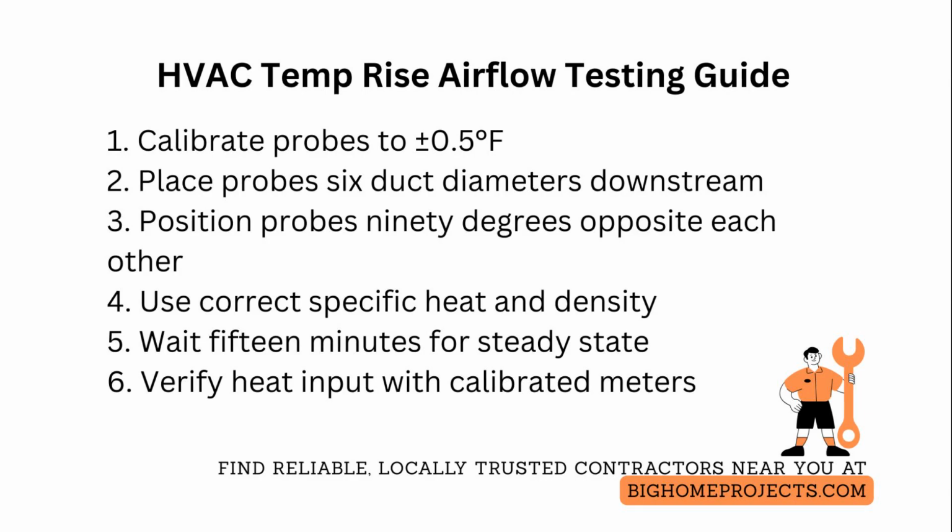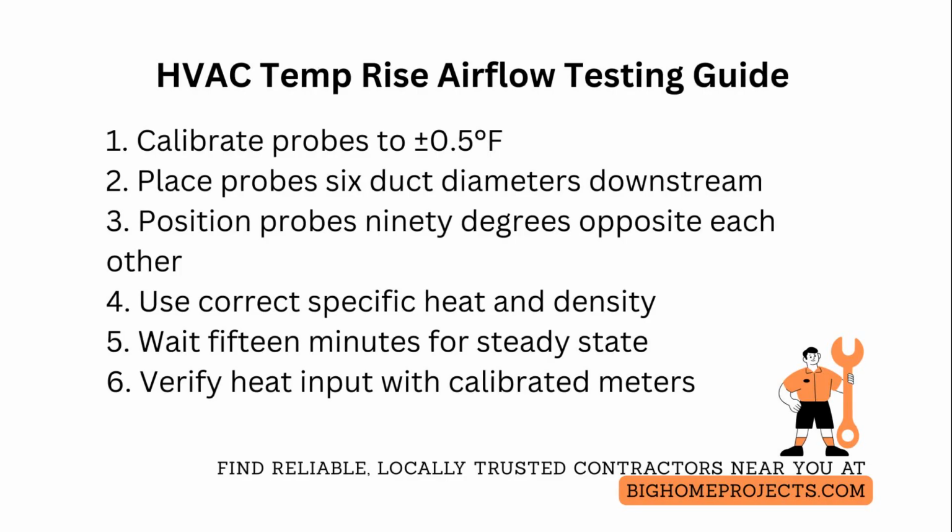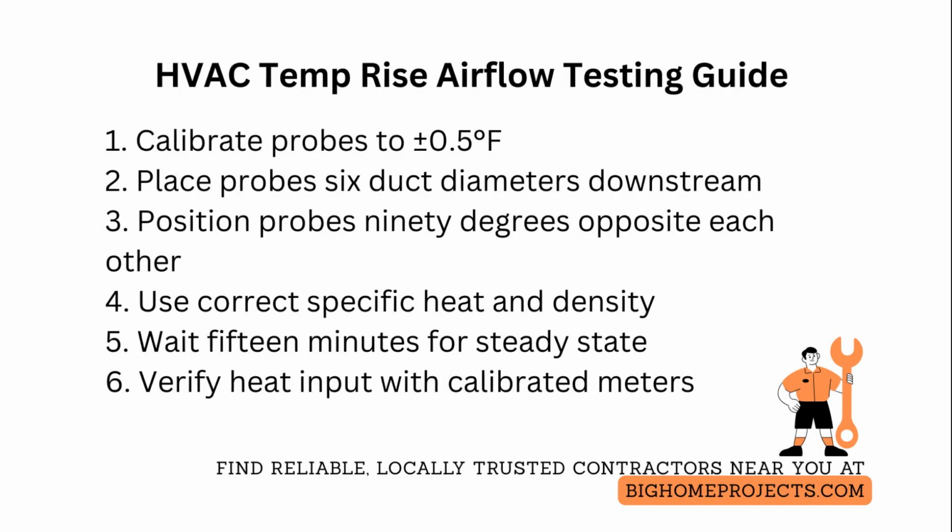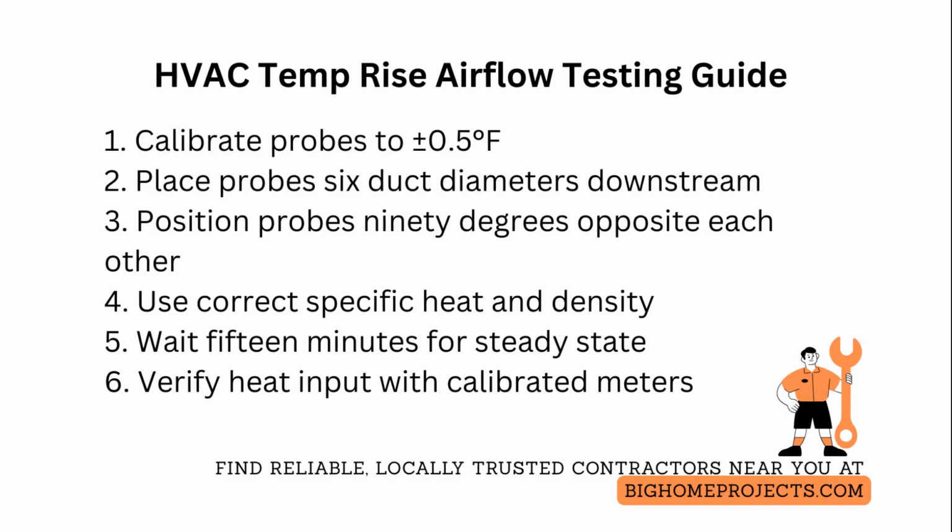And always verify heat input with a calibrated power meter or gas meter reading combined with combustion analysis for fuel-fired systems. Account for heat losses in long ducts by measuring static pressure and adding an offset if the system exhibits high leakage or flex run loss. Ignore this at your own risk.